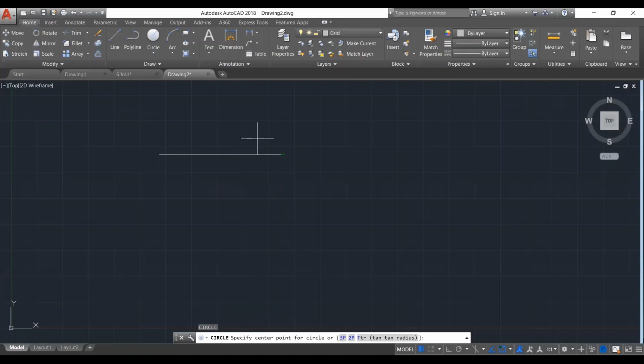Here is another important point in the CAD, and it is one of the most important points that give the CAD high accuracy. It's called the snap options. You can find on the ends of the line small green squares appearing when the mouse is here. And when I become near the midpoint, you will find a small green triangle like this. This triangle means that I'm stopping on the midpoint of the line, and this square means that I am on the end point of this line.